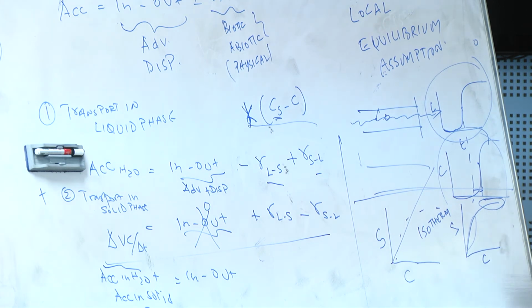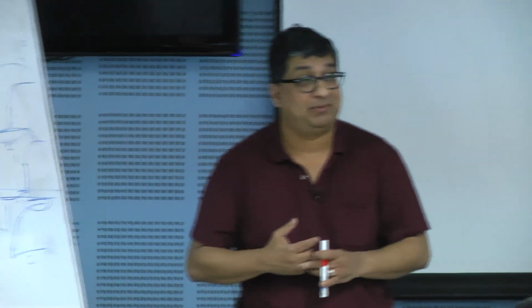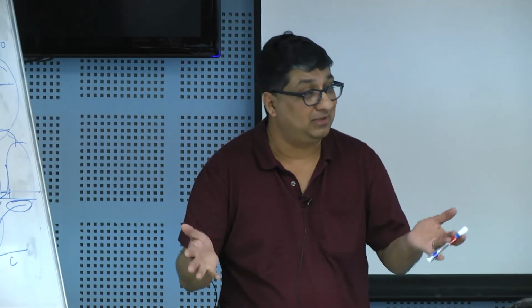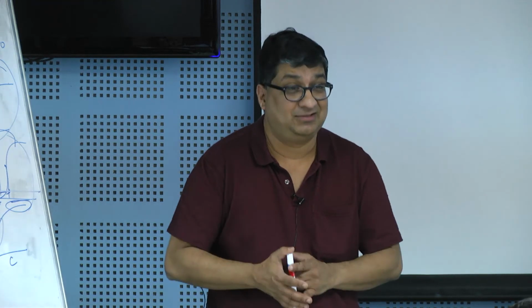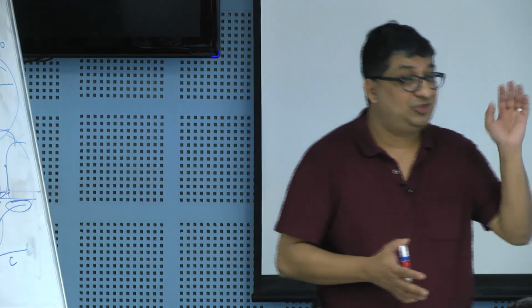Okay. So, this can be modeled using a variety of different types of models. Most common models are Langmuir model, Freundlich model, there are whole others. Yeah, there's a whole bunch. So, Brunauer, Emmett, Teller, or whatever, BET model, there is Temkin model, so. But the most commonly used ones in groundwater are linear, Langmuir, and Freundlich. They all come from different. The Freundlich and Langmuir do the adsorption process. Linear does the absorption process.